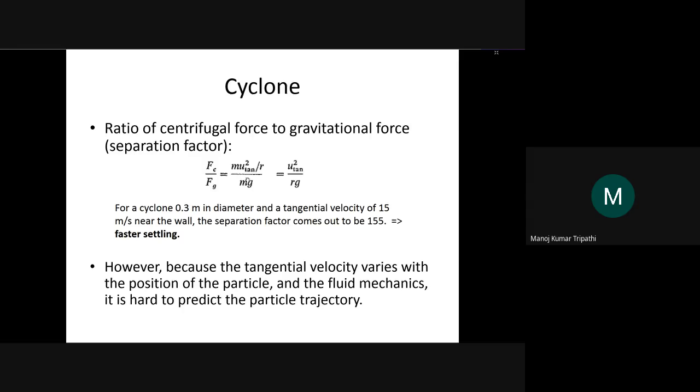Let's say there is less centrifugal force and more gravitational force, then it will pull down fluid and particles without them being separated. They won't have much time to separate, but it will pull down quickly. So we want less gravity and more centrifugal force. That increases the separation. It gets more time to separate.